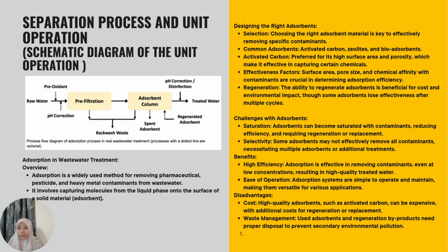For the overview, adsorption is a widely used method for removing pharmaceutical, pesticide, and heavy metal contaminants from wastewater. It involves capturing molecules from the liquid phase onto the surface of a solid material. For the challenges with adsorbents, an adsorbent can become saturated with contaminants, reducing efficiency and requiring regeneration or replacement.